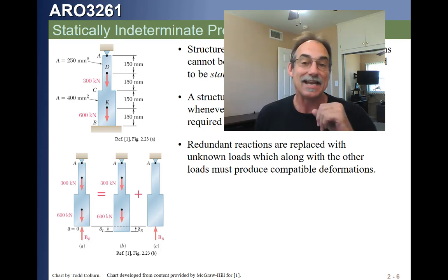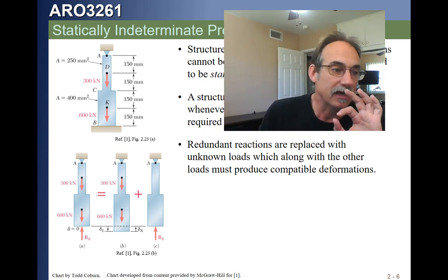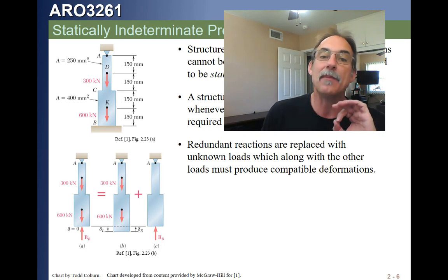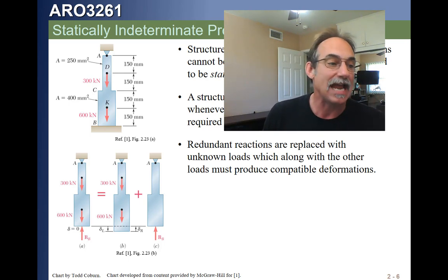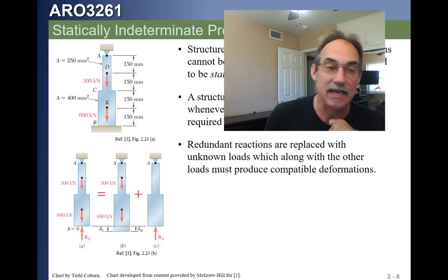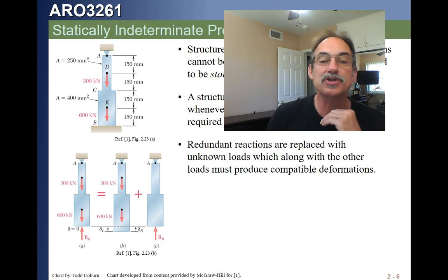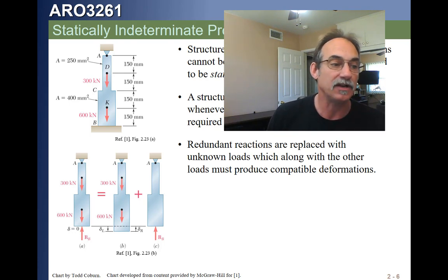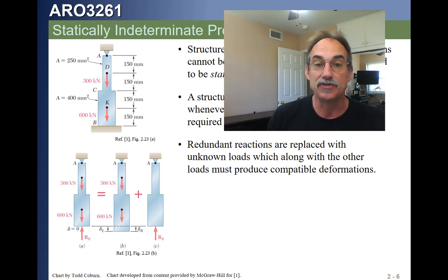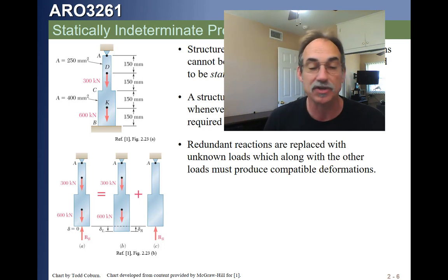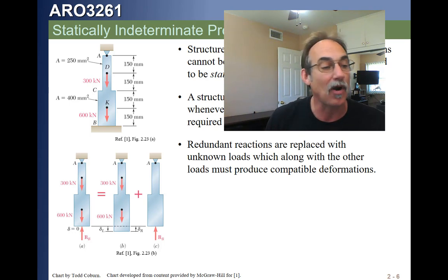Now, the part cannot deflect that way. So then we apply a reaction force to the bottom. It's shown as RB. And we're going to use that force to eliminate that deflection. So the total deflection under this force RB is going to remove that deflection. We can now take the deflection under that force. If RB is applied, then the reaction at A for that force is also RB. That means this entire part is now under RB in the second case.